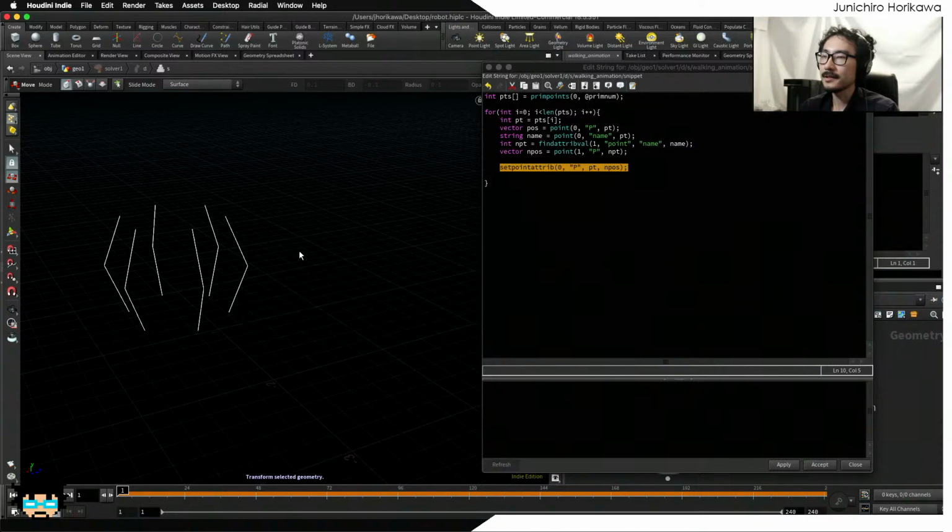Since this is going to be just a guide, this middle point for the IK targets is just going to be a guide in which direction this leg should be bent. So making this line long ensures that this leg always bends outward, not inward. So that's what I want to do for the middle point. I just want to move this point position outward a little bit longer than the original position right here. Okay, that's what I want to do.